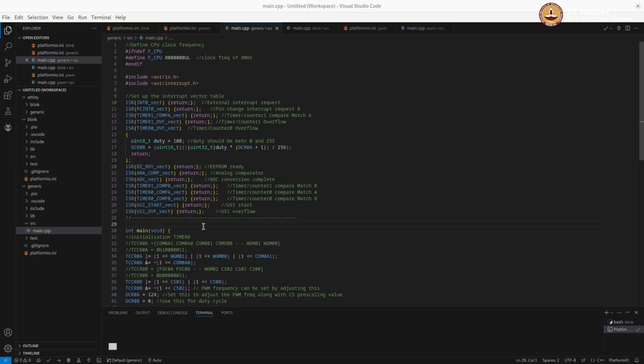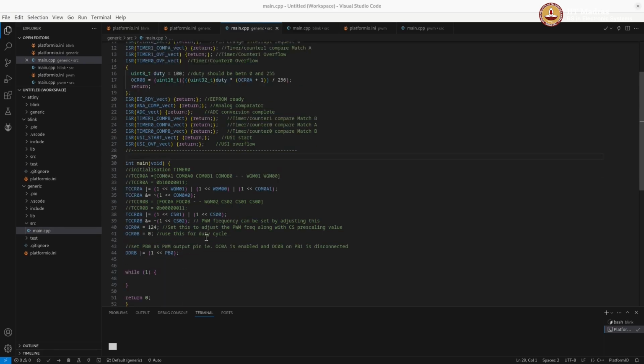Another important block in the microcontroller that we will almost always use is the ADC block. So let us learn how to initialize the ADC also. Let me make space there. After the initialization of the timer set of statements, I will say initialize ADC for free running mode.